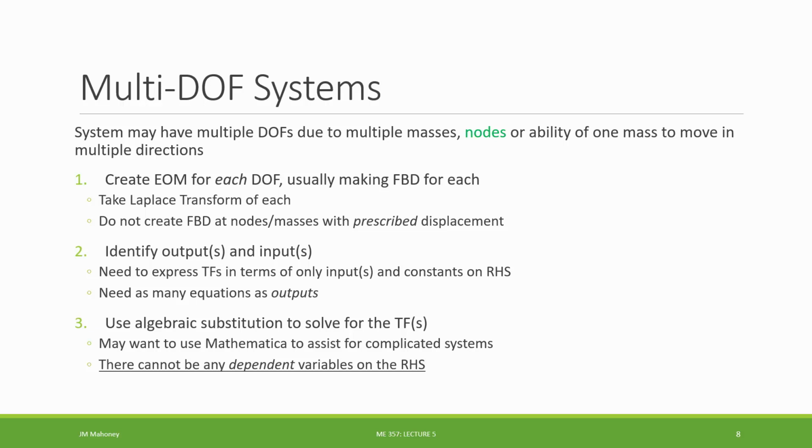And this is going to be done to make it much easier to then simulate our results in MATLAB. As in MATLAB and in other systems that have or support transfer functions, they are expecting you to put in the coefficients of your transfer function in descending powers of s. So we will see that in the first two examples we look at using transfer functions and then simulating their results in MATLAB.